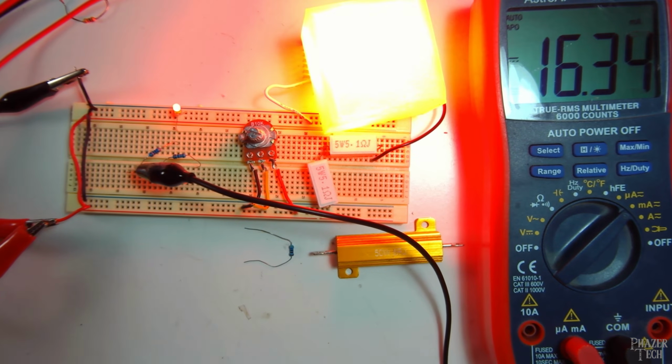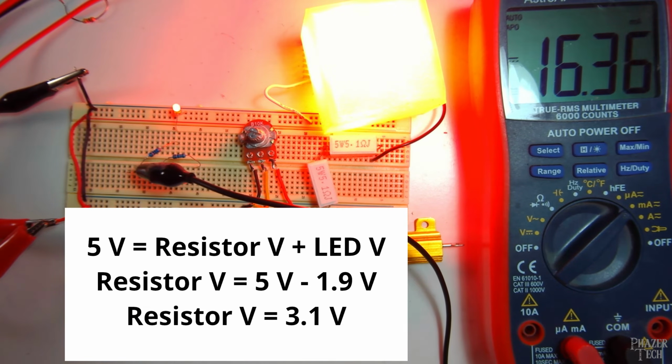So there you go. Now keep in mind that this is running off a 9 volt power supply, which doesn't do us any favors when it comes to power efficiency. A 5 volt power supply would make a lot more sense here, since the voltage drop across the resistor would be 3.1 volts instead of 7.1 volts like it is now.